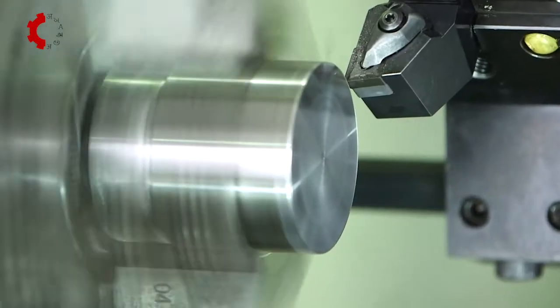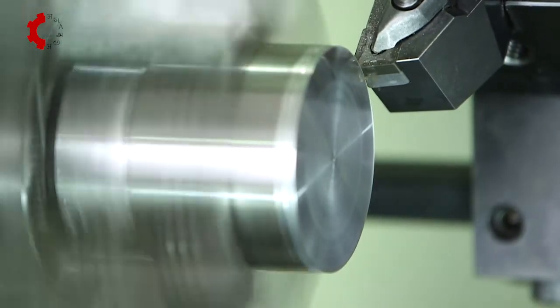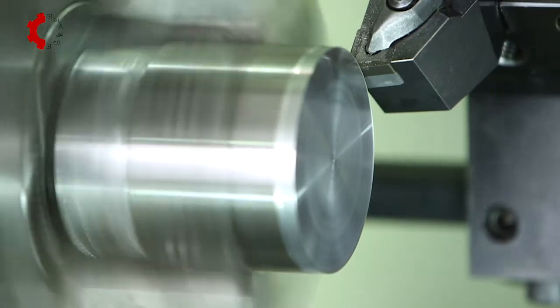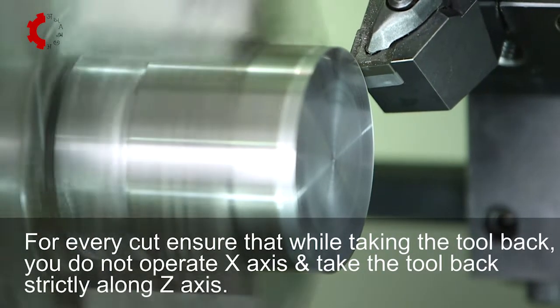Switch MPG to Z axis and take a cut on the OD for a sufficient length, say 10 to 12 mm, so that correct measurement of diameter by vernier or micrometer is possible. Repeat taking cuts on diameter until the workpiece diameter is cleaned.